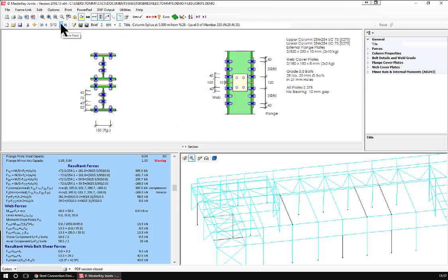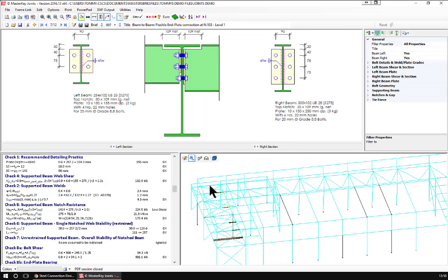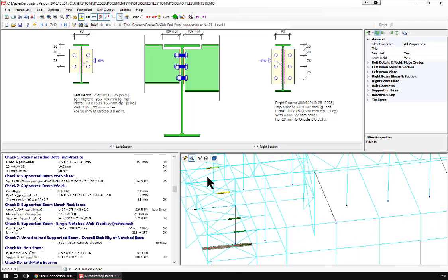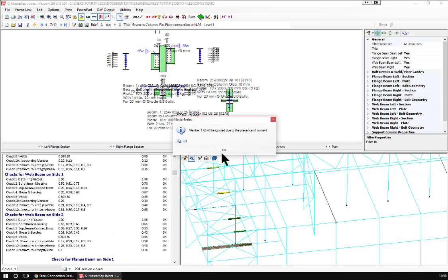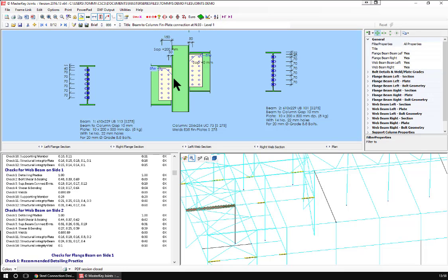And then of course we have our column splices and our alternate column splices and our flexible end plates, and then here we have 1, 2, 3, 4 flexible end plates that are matching. Sorry, 3. That one is not matching, even though it was meant to be in the same group. And just moving forward, we have another connection with flexible end plates onto a column, and you'll see that the others are not matching because every single one has different section sizes coming into it, so it says no, do them all separately.